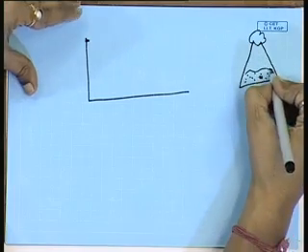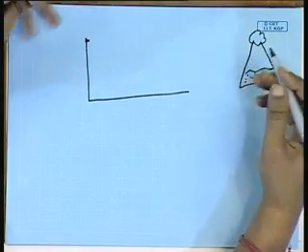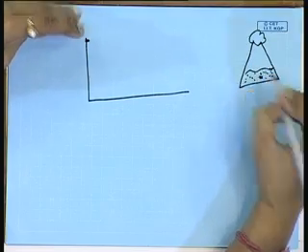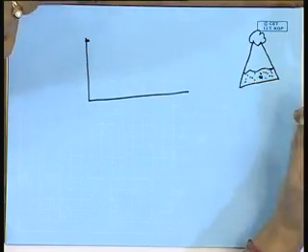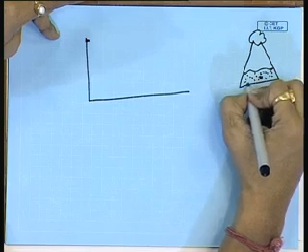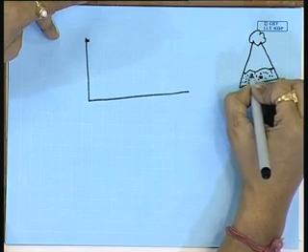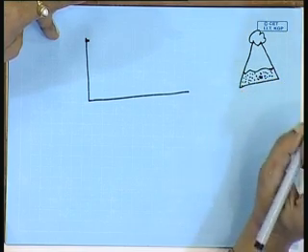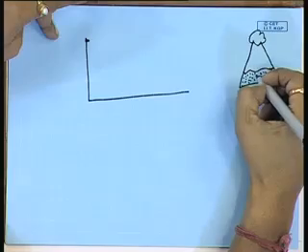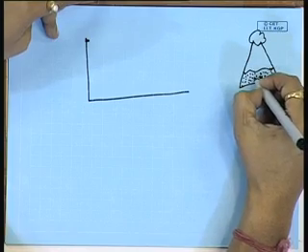What is happening when these metabolic activities of the cell start inside this reactor system? The nutrient carbon, nitrogen and other minerals inside this reactor are continuously being taken up by the microorganism. As a result, what is happening? The number of bacteria, the number of cells, or the biomass concentration is gradually increasing, and the carbon and nitrogen content of that medium is gradually getting depleted.